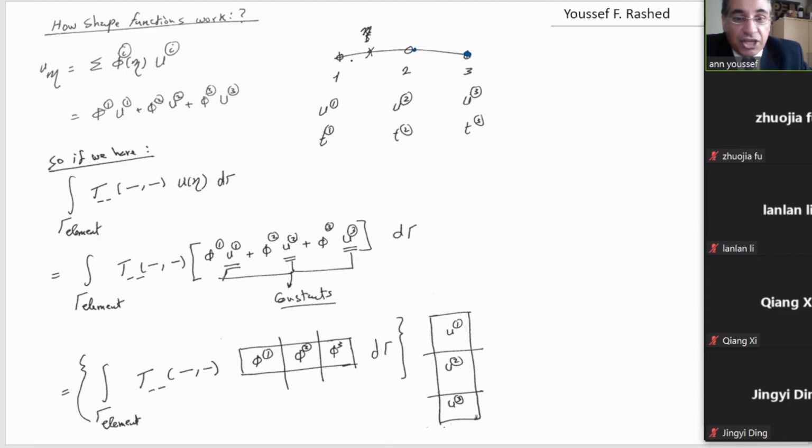Okay, so the idea, if you remember, in quadratic element we have 3 nodes. We have in each element 3 nodes, and we have direction here called eta. Here eta equal +1, and here eta equal -1, and at the middle eta equal to 0. Remember, one time we'll place this node in the quarter point to model fracture mechanics. I will show you how to do this. This is called the quarter point element. Okay, we can do that in finite elements also.